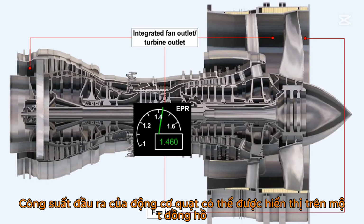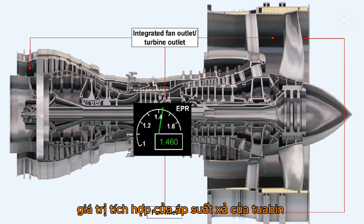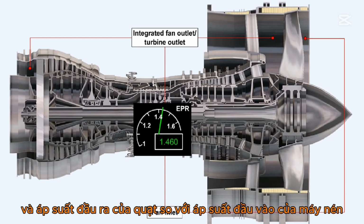The power output of a fan engine can be shown on a gauge which measures the ratio of the integrated values of the turbine discharge pressure and the fan outlet pressure to the compressor inlet pressure.